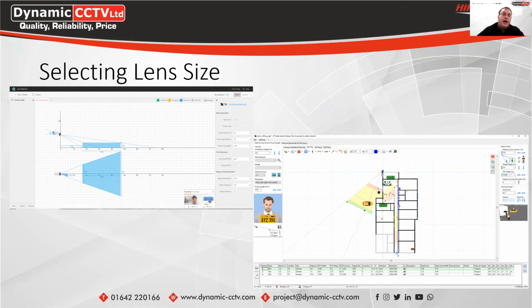But the best way to make sure that the lens size is correct for the system or the environment is to use the Hikvision lens selection tool, which we're going to take a look at in a moment, which you can see on the left hand side there. So you can put in your target detection distance, where you need to be able to see, the mounting height of the camera, how high you can mount it, and then you can select from a wide variety of different cameras and lens sizes, and it will give you an example of the pixel density that you would achieve at the distance that you've set.